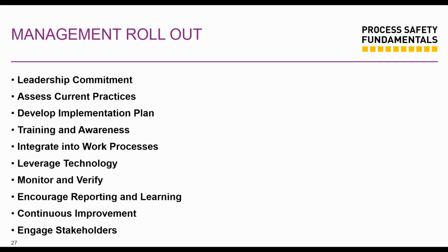when we're discussing. And then the fifth is integrate into our work processes. So all these PSFs, we integrate them with our lockout tagout procedures, our gas testing procedures, our hot work permits. Use these work checks to ensure safety barriers are in place before the tasks begin.